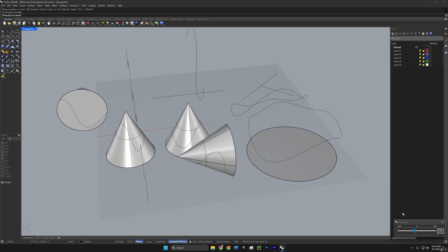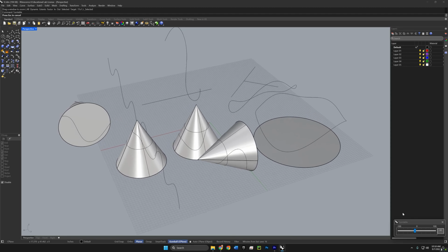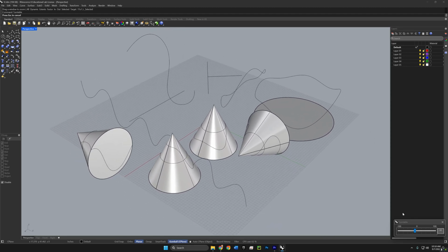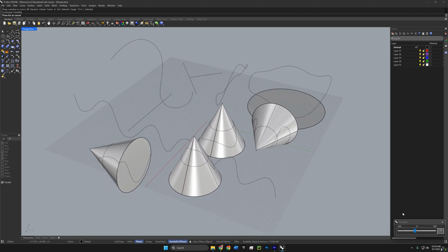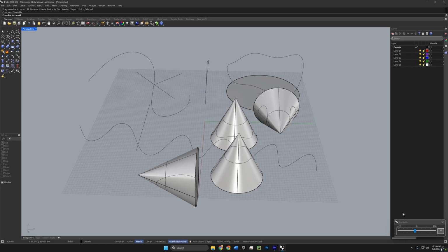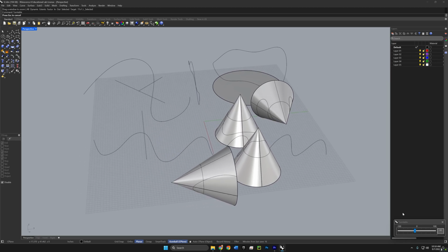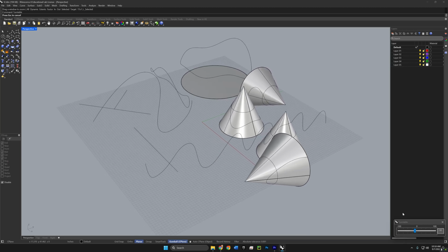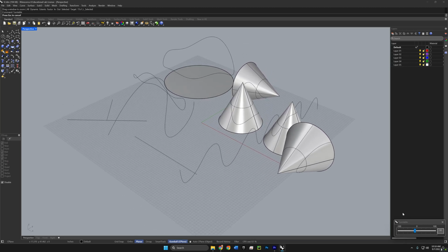In this short video, we'll take a look at how construction planes work. To illustrate the impact of which construction plane is active, we'll go over the project command, and we'll cover a command called project to C-plane that's used for flattening geometry. Note that at times in the video, I'll refer to C-planes. This is just a short name for construction planes.